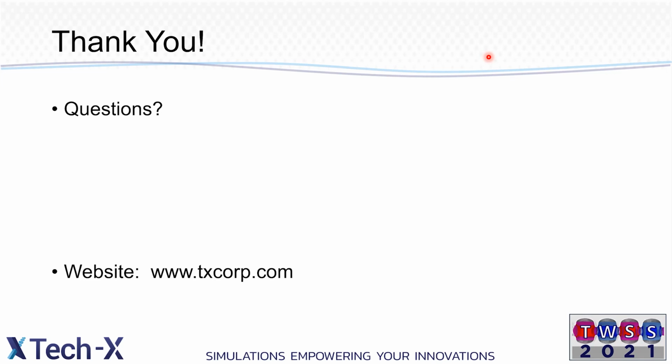How do you treat the various different scattering mechanisms, like phonon scattering? This is a very classical fluid model, so we have essentially a collision frequency. You take each of your collision mechanisms, like impurity scattering or phonon scattering, and each is going to have a mobility associated with it. We turn the net total mobility into a collision frequency.